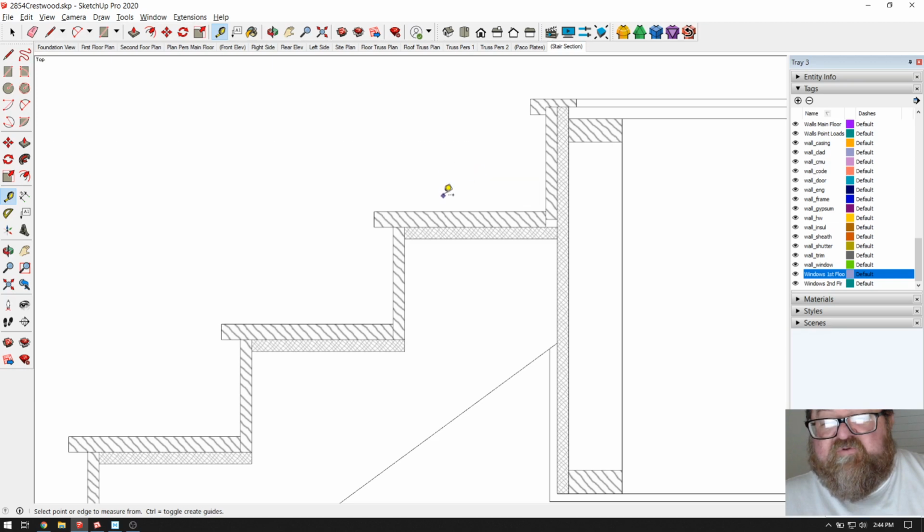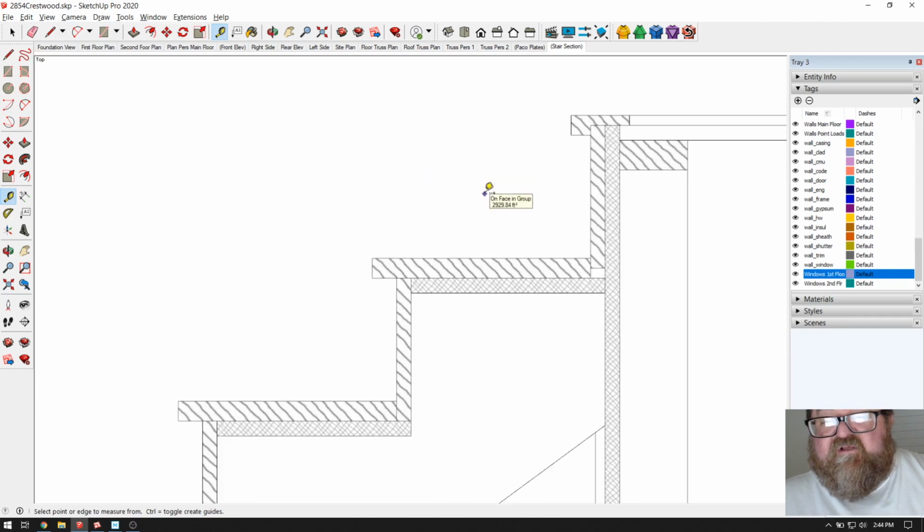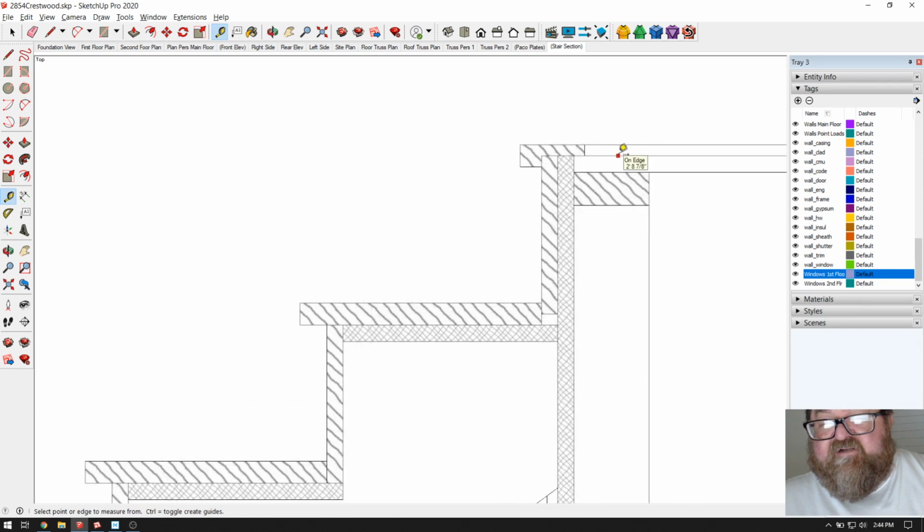Let's say, for example, if I had used 7 5/8 for a riser height, and I had planned on this 1/2 inch, if the owner ends up doing like a hardwood and adding a 1/4 inch thickness to this, all of a sudden I'm breaking code. I've got a code violation on my hands, okay? Because that pushes my riser over 7 3/4. These are all the complicated issues. They're not complicated if you plan them, okay? The most important thing, remember, is that you have to determine and just stick to this thickness. It doesn't matter what it is, okay?